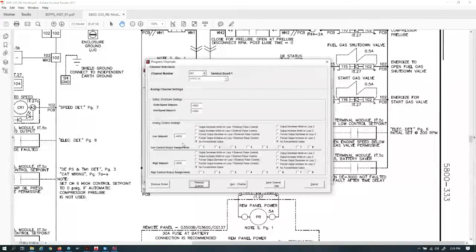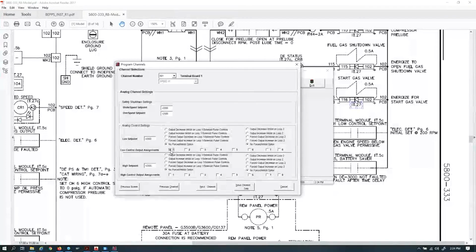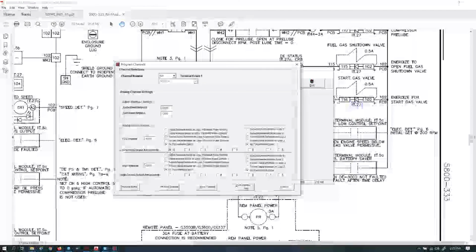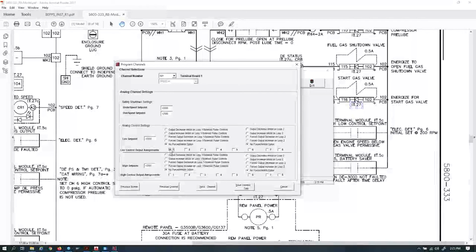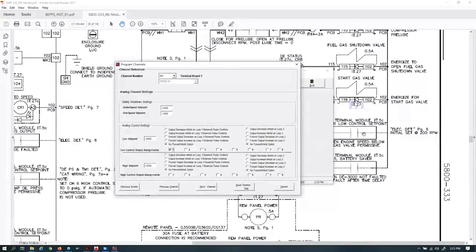What we're looking for in this case is a low RPM control set point set to turn on digital output 1. So there's the checkbox that I'm telling you some people forget why it's on, and they might uncheck it. We have that happen quite often. People get into these programs and they don't quite understand what's going on. So if that's unchecked, that digital output will never work.